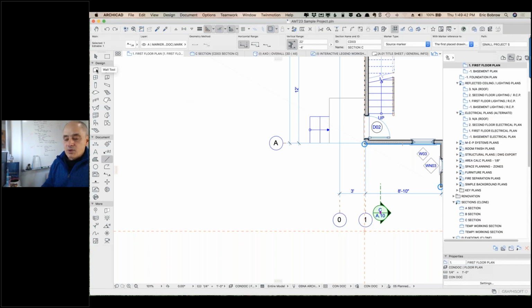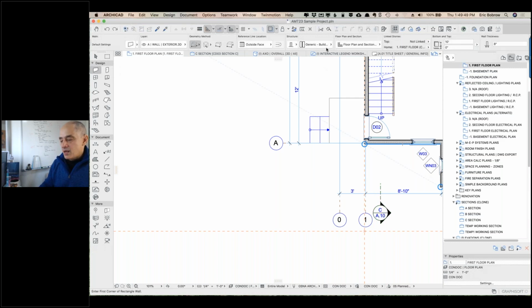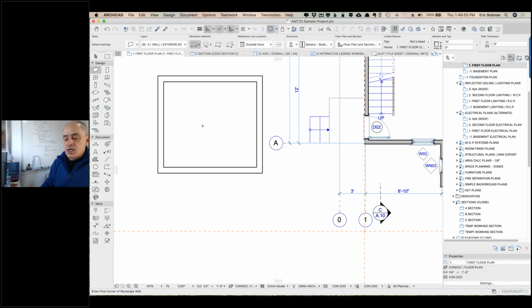All right, so I'll just create a bounded area. So we're going to take the wall tool, and right now I've got some generic walls. I'm just going to draw a box like this. Okay, so here we have a box. Now, if I go to the slab tool, the slab tool can be set to whatever. Right now its top surface is at 0, so it would be a floor, and it has a certain thickness. Let's just put in a floor here.